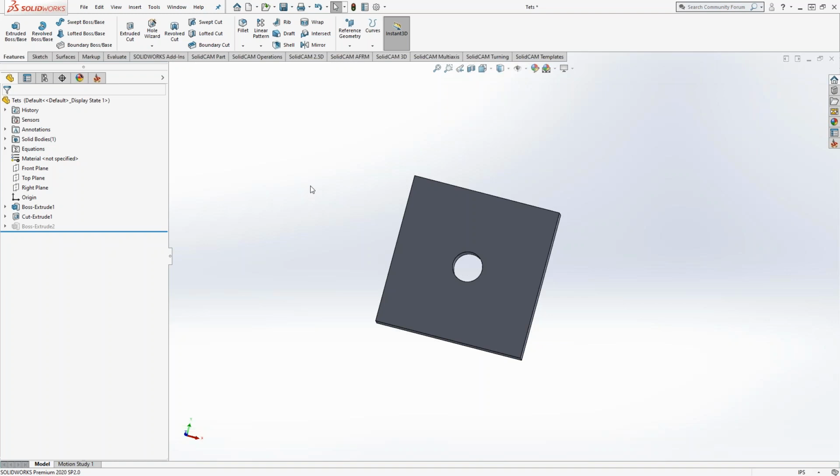So if you have a fully assembled part, the target sitting inside of soft jaws, and now you need to change those soft jaws to match what the part is, then you can just take a variable from your part file in that assembly and then just relate it to the part file from the assembly that makes up the soft jaws. And then an arc that represents something on the soft jaw could be just a value that you take from your part file. That way you don't have to go and remate everything. You can just say one face is tangent with another face, or one face is coincident with another face, and then as soon as all those variables line up, the whole thing will change, but because you've intermingled and related everything, it'll just morph itself into the shape that you're looking for.